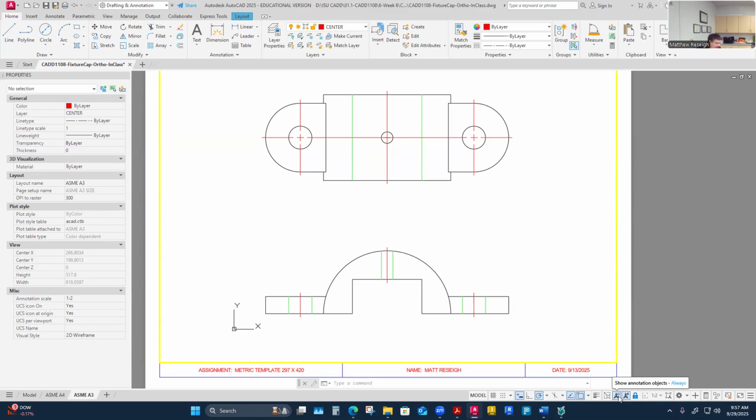What I mean by flexing them is, and that's maybe the term Revit uses when they build families, maybe somebody's built a window for you and they want you to be able to upload it to your house. And then they want to give you a few controls where you can change a few things. Families in Revit are built to be flexed. They build them parametrically, so that maybe a few data inputs are needed to resize a window and everything else will auto adjust for you. That's the idea of parametric modeling, by the way.